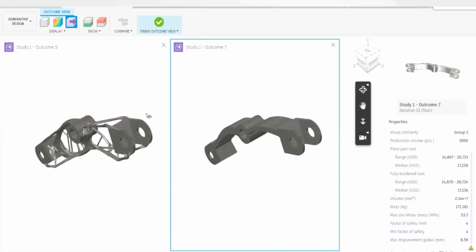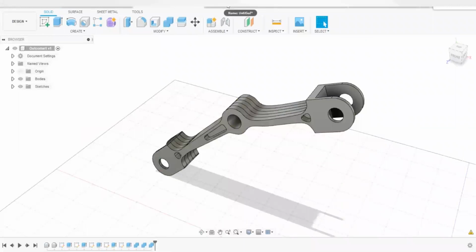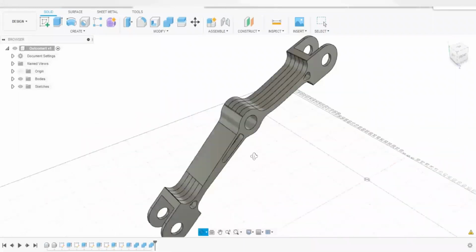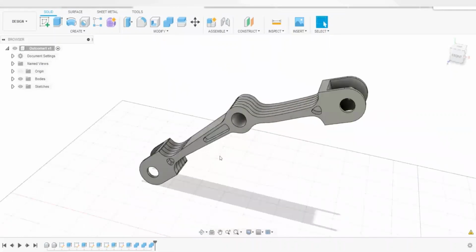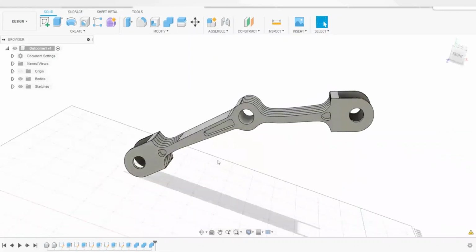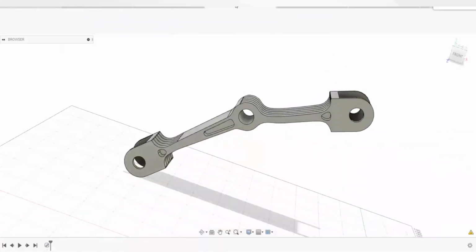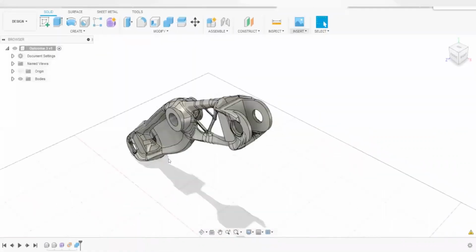Once we have chosen the design that we'd like to use for the front loader, we can actually generate this as a CAD model. So I do have a couple of these outcomes, and once again, these are CAD ready and CAM ready solutions. So from this point, we could actually take it into simulation to do all the tool parting for the manufacturing that will take place in creating this arm. So we have 1, 2, and 3 outcomes.